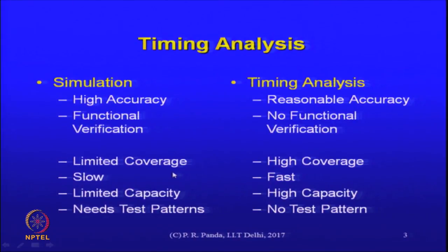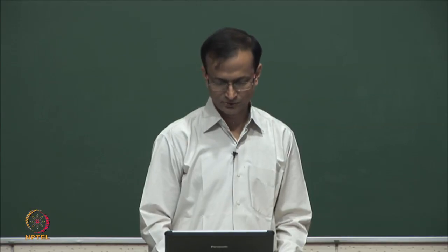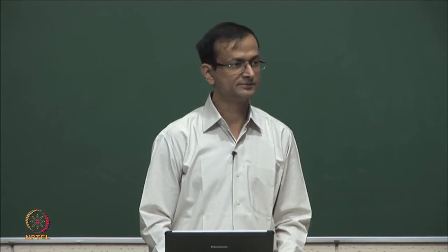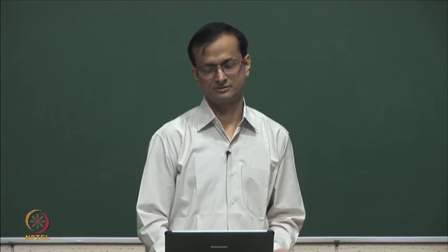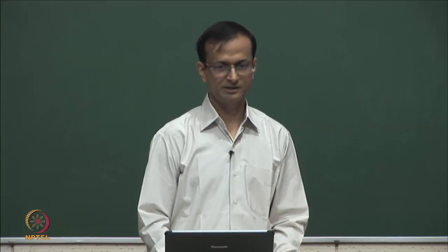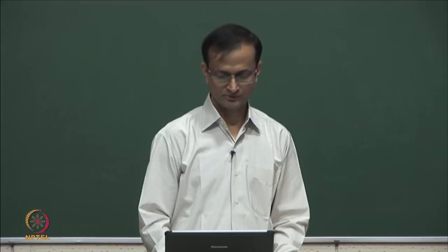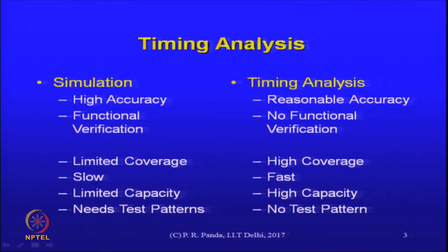Coverage. We say limited coverage versus high coverage. What do we mean? You need to provide input vectors for the simulation to work, and of course, we are limited by how extensively we can generate those vectors, how comprehensively we can simulate the circuit with the vectors, just because there are way too many vectors to test. But in timing analysis, the coverage could be much better because you are making a strong statement that irrespective of what the data is, your circuit has only so much delay.